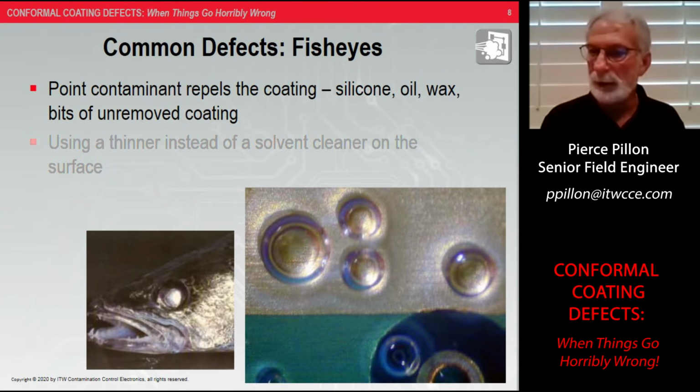When it goes through the cleaning process, it's washed off, the binder's dissolved, releases either the clay or the cellulose, and then it goes where it goes, down the drain. But if you don't adequately clean it, now you've got little spots of clay, and these are very small particulate size of the clay or the cellulose. Those could be point contaminants.